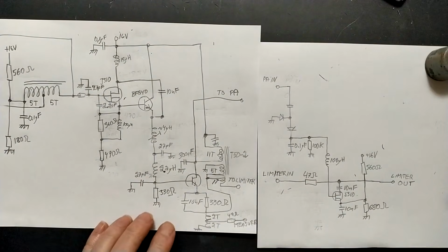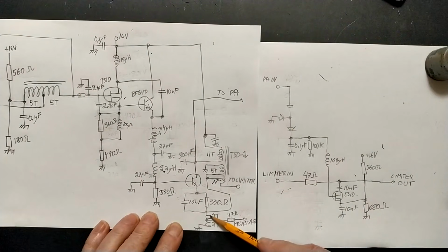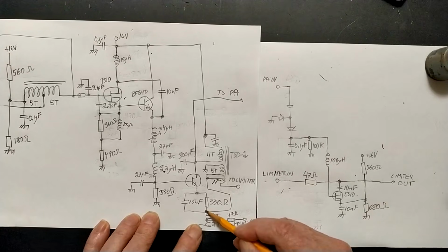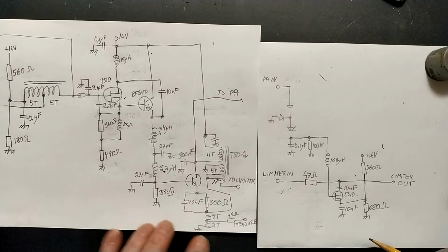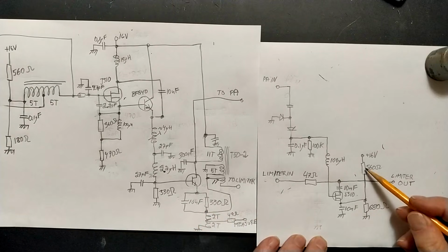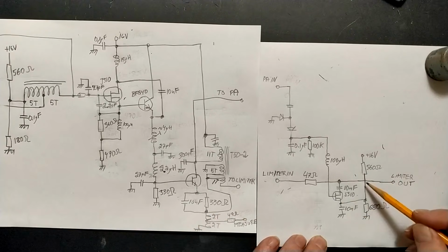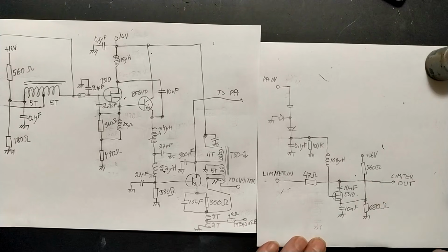And this gives a constant signal level at the output. I am measuring the signal through a step-down transformer here, 4 to 2 turns, and a 47 ohm resistor to set the impedance to fit the measurement system. And of course, the voltage divider for the channel voltage of the FET is not connected to the limiter output. That was a drawing error.